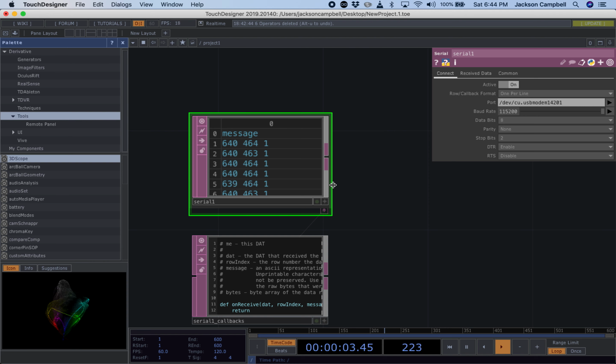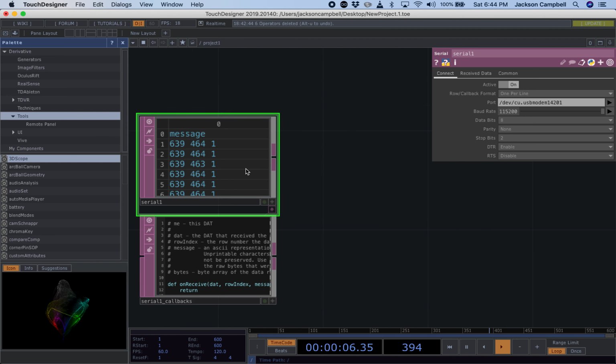You see there is still a little bit of glitchiness. You'll see some weird values pop in here, and later I'm going to do some filtering to help keep those from getting into our system. I have found that it's difficult to 100% eliminate those glitches, but you can usually filter them out. It's because serial messaging is not packetized data, it's a serial string. So if the timing gets off through some lag in the system, it can mess up where the message is sent or how long the message string is, because it misses the end of line character or something like that.